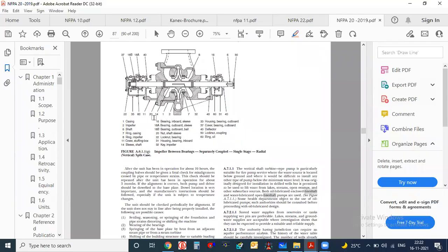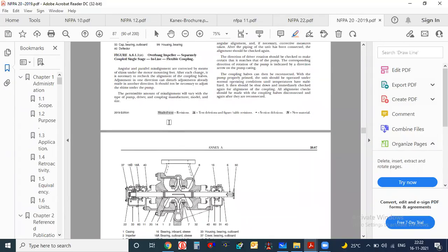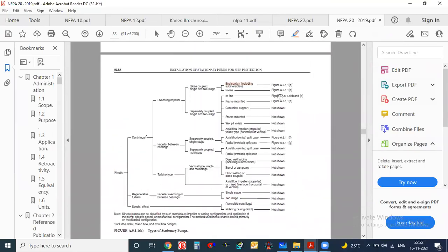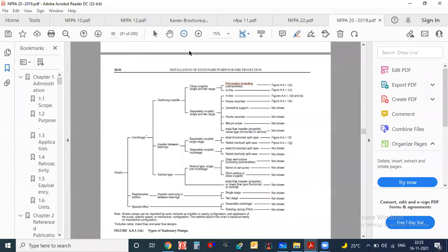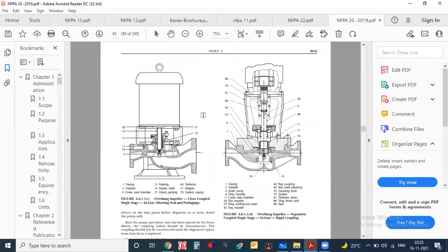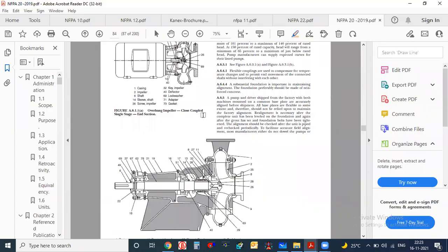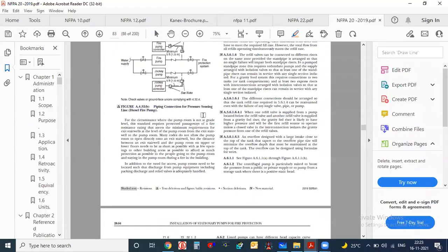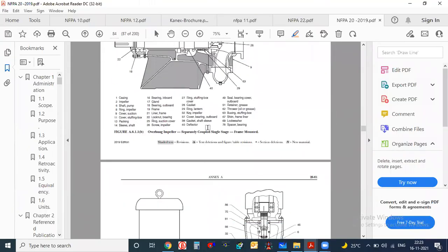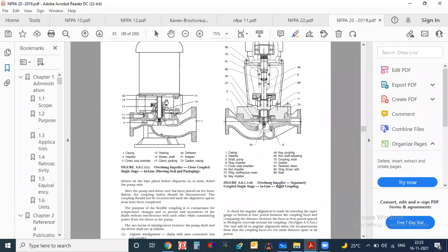If you check the above documents, here they have given the construction of the pumps, different types, and the references. Some pumps are shown, some pumps are not shown. Out of the figures given, the most important pump is the end suction, because normally our pumps are end suction or sometimes inline. These are the two pumps which we normally use. And suction means vertical to the discharge, right? Vertical 90 degree was the suction, right? Yes, I will show you. See, this is the inline.